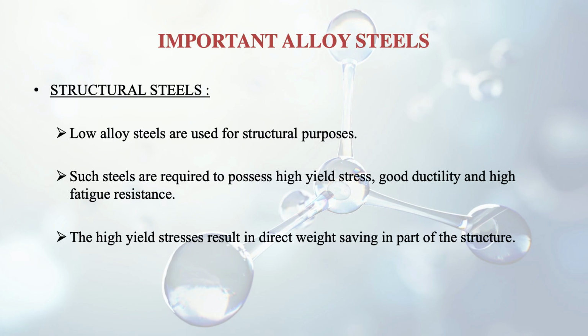So ductility is very important, and fatigue resistance is also very important, because there are different kinds of loads which these structures have to bear, like wind loading and so on, so we need to have high fatigue resistance. Then the high yield stresses will also result in direct weight saving in parts of the structure.